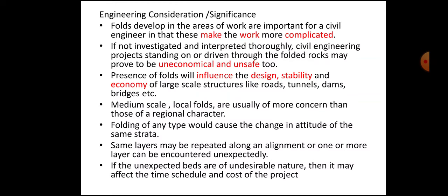Folding of any type will cause a change in attitude of the same strata. Same layers may be repeated along an alignment, or one or more layers can be encountered unexpectedly. If the unexpected beds are of an undesirable nature, then it may affect the time schedule and cost of the project.